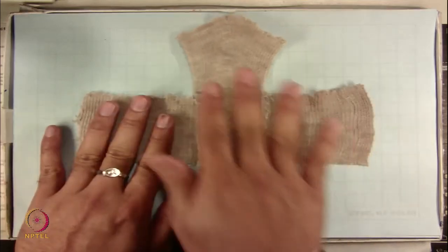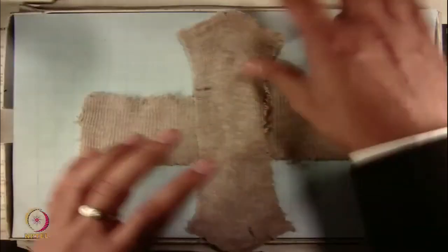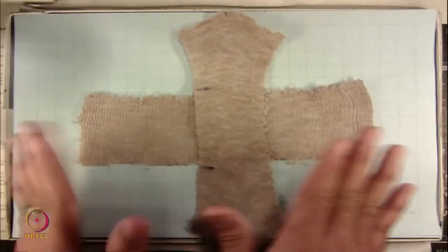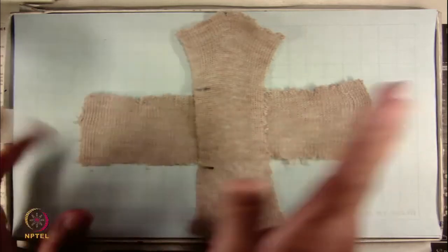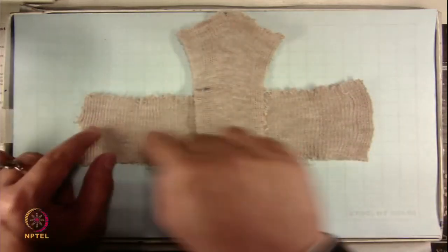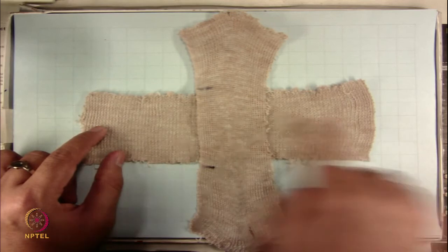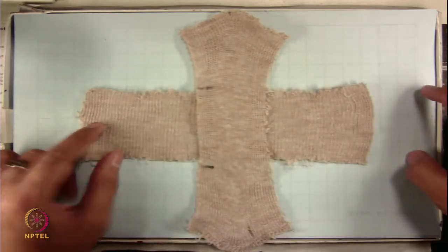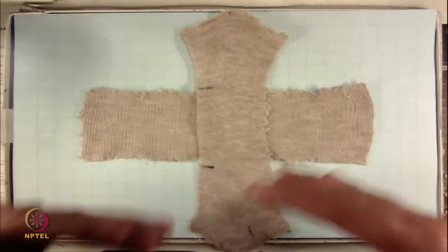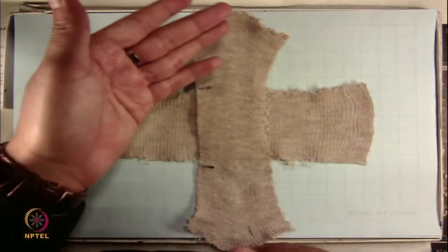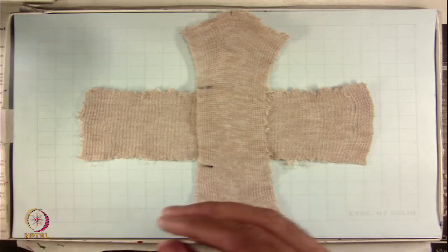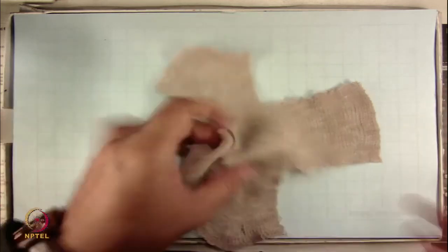If you really want to achieve stretchability exactly the same in all directions, then you have to play with the structure carefully. So, let us see what will happen if you change the loops or stitches inside this fabric. What will happen to stretchability, whether it will increase or decrease. Similarly, in wale direction whether it will increase or decrease, it will again depend on the stitch type, whether you are including loop, tuck or float. I am going to show you in a couple of slides.